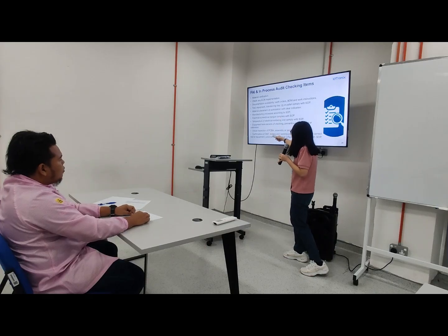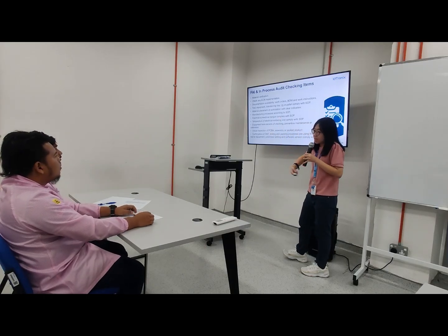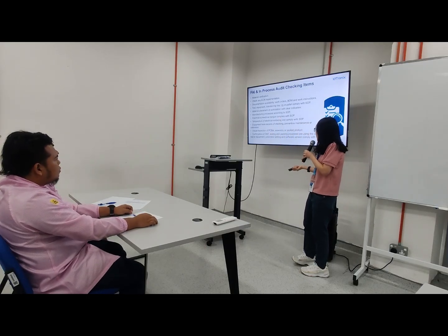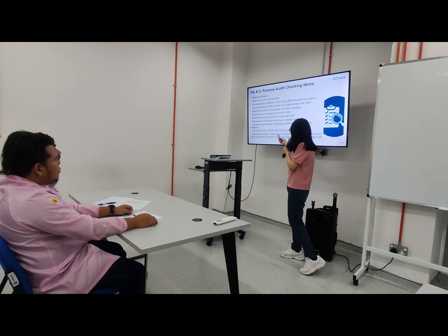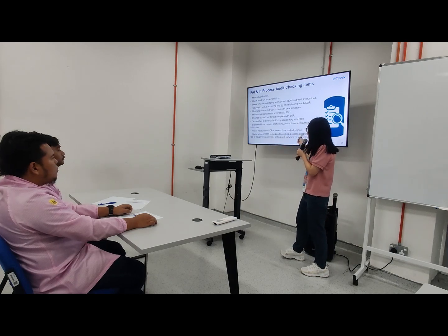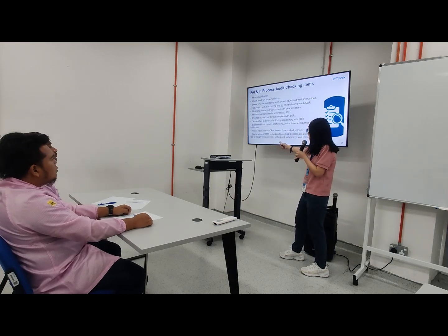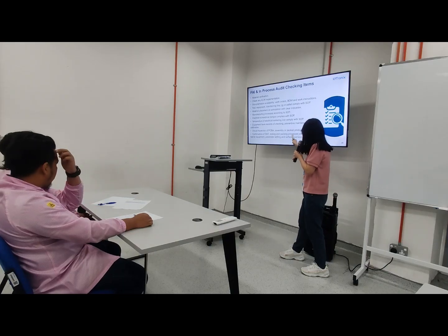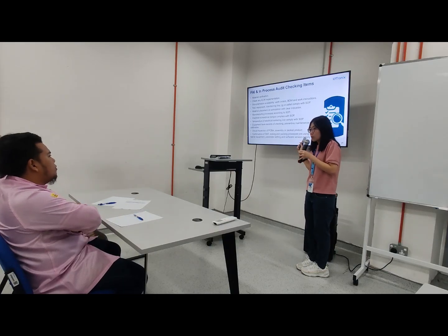Then they will also conduct a visual check for PCBA, SMT or packing, and confirm that SMT, testing and packing processes are using the correct tools, equipment, parameter settings and also software version, the same as the SOP or not.